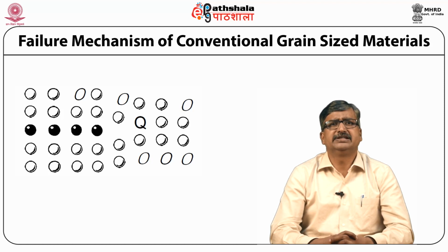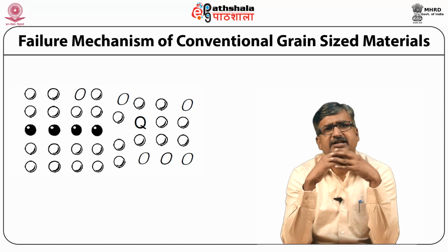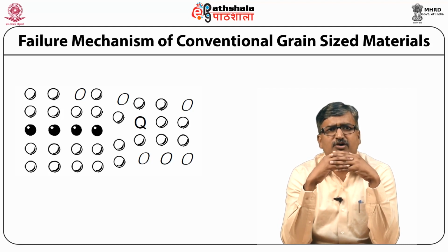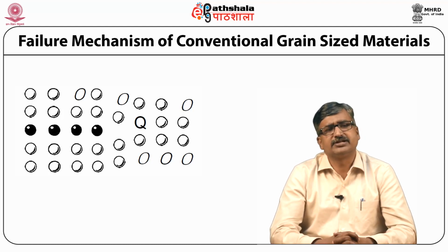One method of increasing the stress at which the brittle to ductile transition occurs is to impede the movement of the dislocation by introducing tiny particles of another material into the lattice. This process is used to harden steel, where particles of iron carbide are precipitated into the steel. The iron carbide particles block the movement of dislocations.